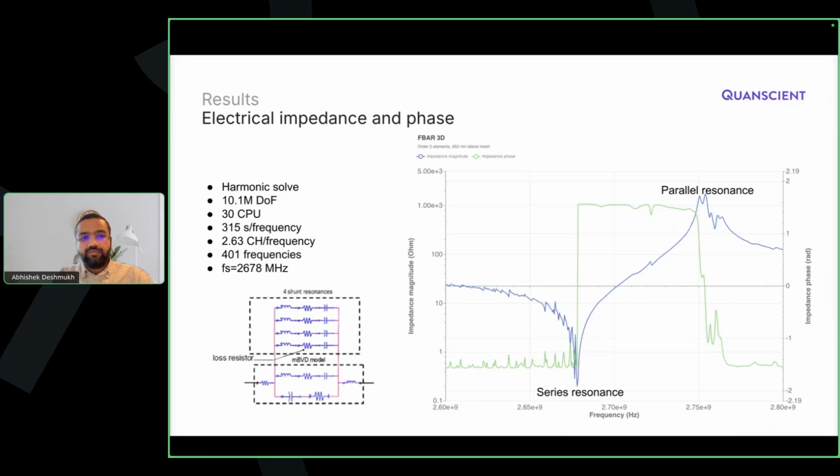And this can be thought of in a circuit analogy. So the series resonance offers the free path to the signal, and parallel resonance essentially acts as an open circuit. In between there is a close match of impedances, and that offers the maximum power transfer between these two peaks. And that's why you get this sharp, stable band, and then a sharp drop at the end of this.